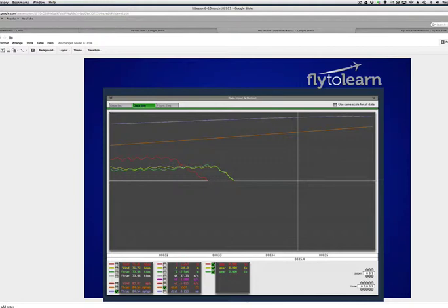Lesson 5 was practice landing, and we did that by just changing the throttle. Set the RPM to about 1600 RPM. You don't want to push the nose down, up, all around. Just try to fly the plane level. You set it at 1600 RPM, it should come in for landing.